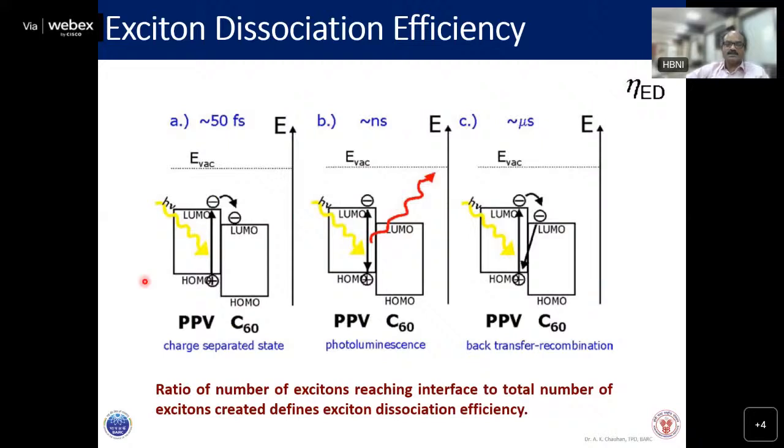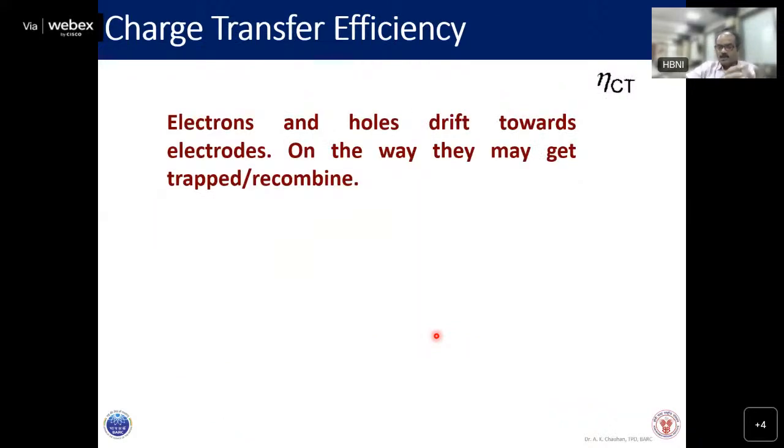These things combine, and actually we can take all three together, because directly measuring the number of electron-hole pairs generated at the interface is very difficult in polymer solar cells, and therefore all three have to be looked at in totality.